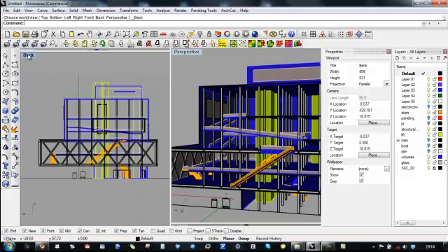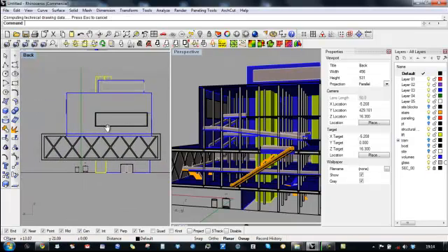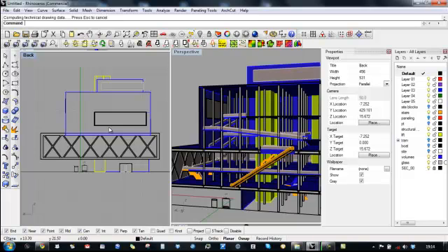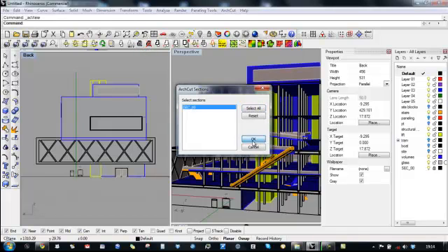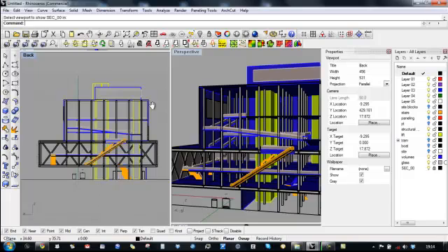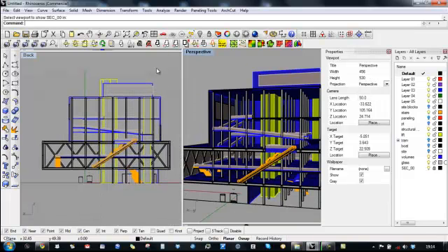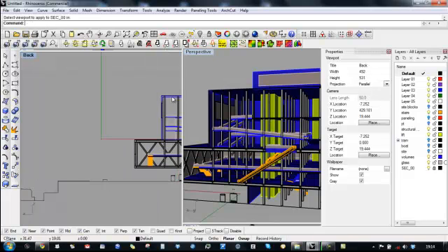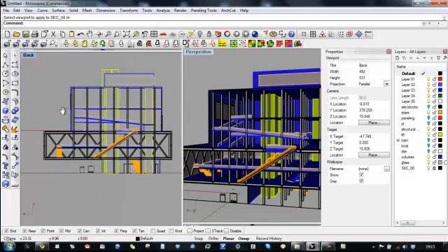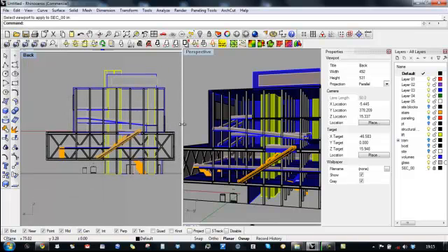and I'm gonna go on technical view. This technical view is actually a plugin that you can download from McNeel for free. And then I'm gonna say I want to see the section here as well. Click in here, and just to be sure, we're also gonna click on set view to section, select the section, okay, and that will make sure that all the lines are parallel to the camera at the moment.